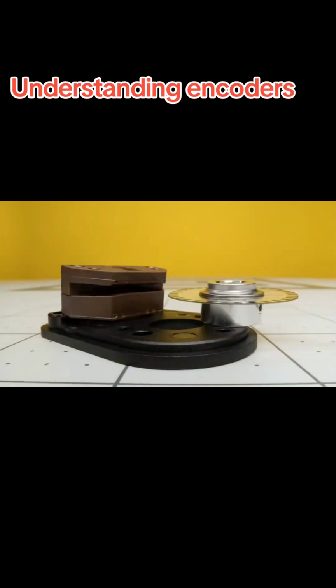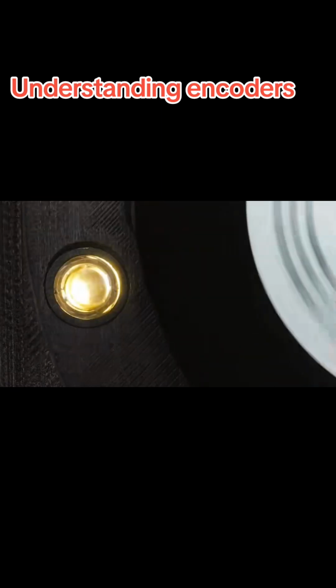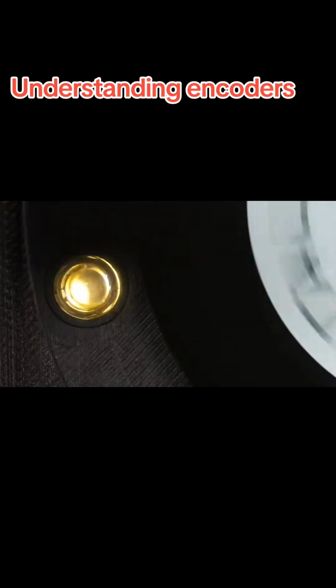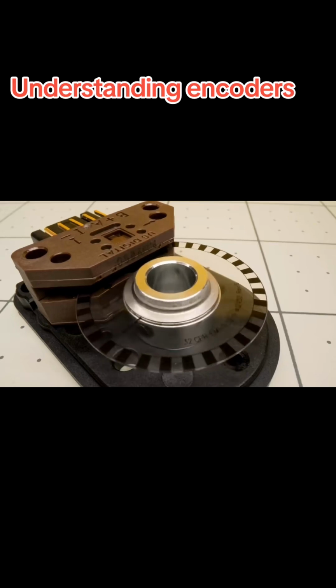The disc has a series of lines on it. These lines block the LED light from reaching the photo sensor, and there is transparent space in between. So this alternating pattern of light and dark is how the encoder reports position information back to the mechanical system.